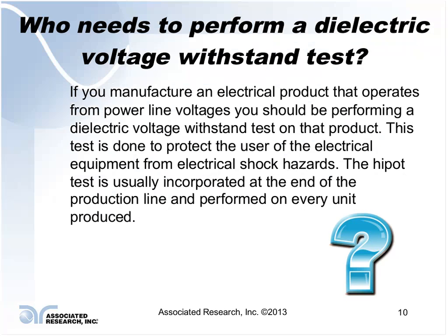The test is usually incorporated at the end of the production line, and it's performed on every product you produce. It's done to verify that the insulation of the product itself is good, that there haven't been any workmanship problems that could have damaged the insulation.